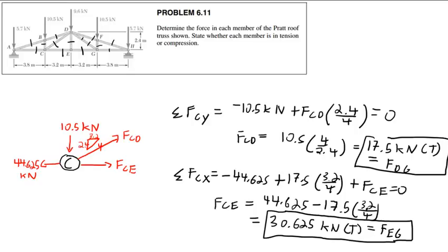In case of a simple truss, we have that m is equal to 2n minus 3, that is 2n is equal to m plus 3, and the number of unknowns that can be determined from the free body diagrams is thus m plus 3. Where did you see that? 288. Okay. Right in the middle of the page. Ah, okay, gotcha. So the number of unknowns can be determined from the...